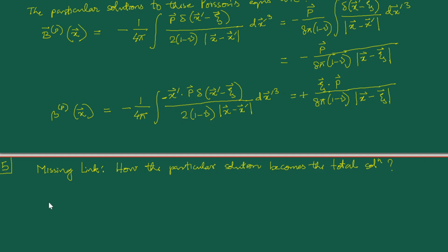So what we'll say is that using these two particular solutions only, we are going to construct our displacement vector. Okay, because you see these help us. So these are part of the Papkovich-Neuber representation, but these themselves are certainly not the displacement vector. So what is the displacement vector? So let me go back to that representation from a couple of lectures back, and just write down the expression for the displacement vector in terms of this b vector and the beta vector.